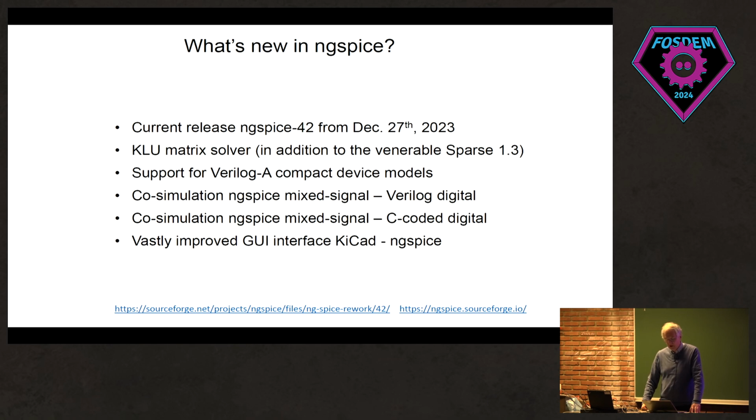We allow co-simulation, again mixed signal, with C-coded digital, so there is a way to translate C code into NGspice readable shared libraries. And I'm benefiting from the vastly improved graphical user interface of KiCad, especially the upcoming KiCad 8, is offering for using NGspice.